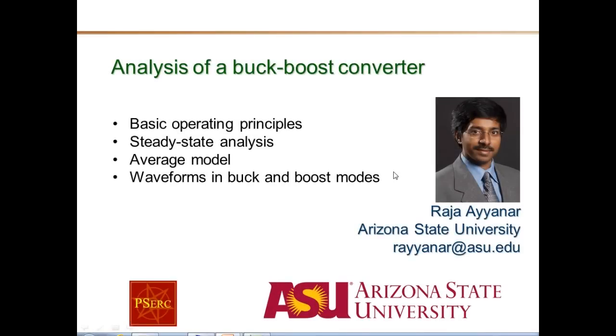A buck boost converter is required whenever we need both a step up capability under some operating conditions as well as a step down capability under a different set of operating conditions from the same converter. So in this video we look at a basic buck boost converter topology and go through its operating principles, steady state analysis, and look at the average models.